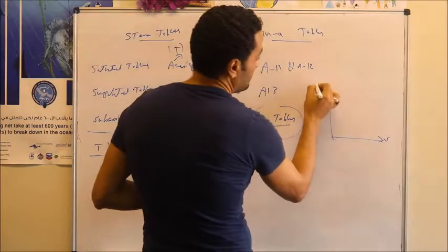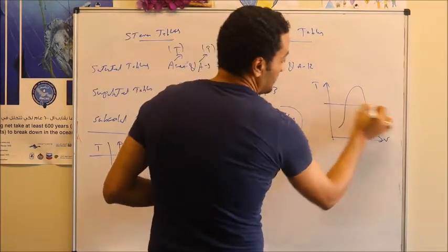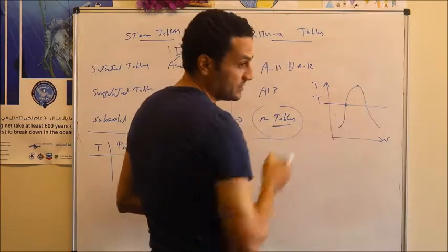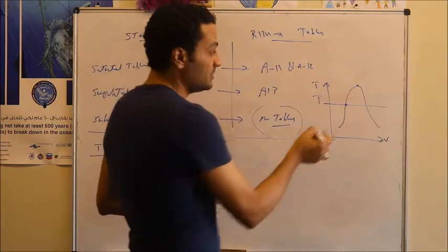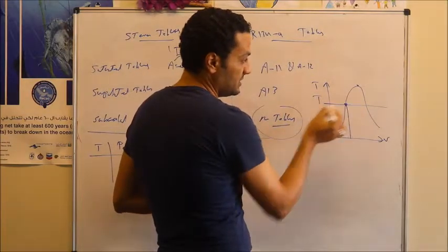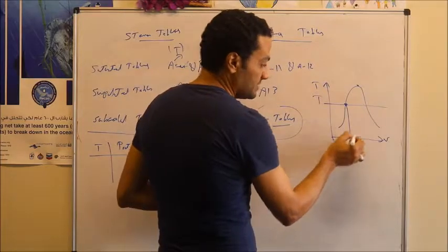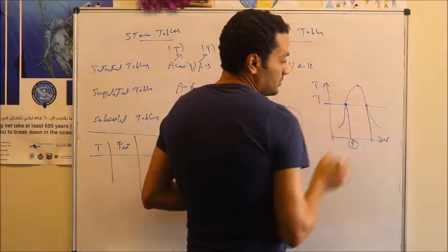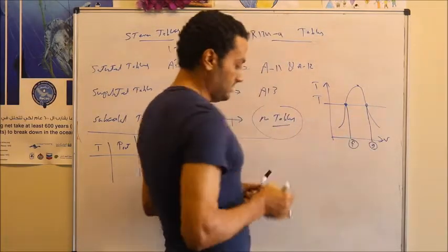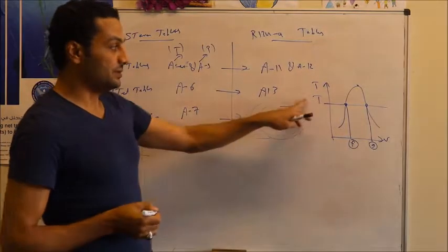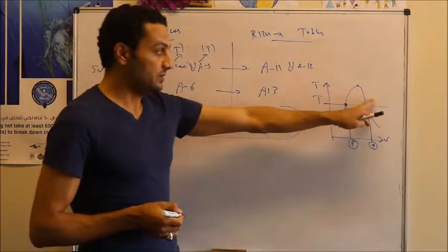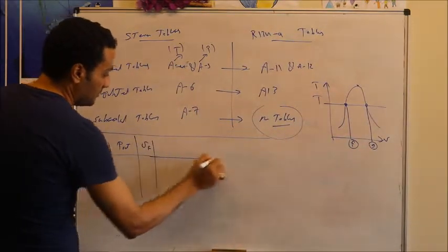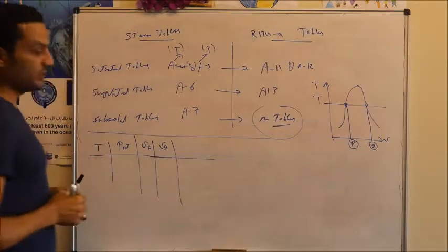If you look at the saturation curve on the T-v diagram, at a given temperature T, the left hand side of this saturation curve represents saturated liquid. So all of the properties at the intersection with the saturated liquid will have the suffix f, indicating the saturated liquid state. Properties at the intersection with the saturated vapor line will have the suffix g, indicating the gas phase. So at a given temperature in this table, the saturated liquid and saturated vapor properties are given. You will see here the specific volume v_f and the specific volume v_g.